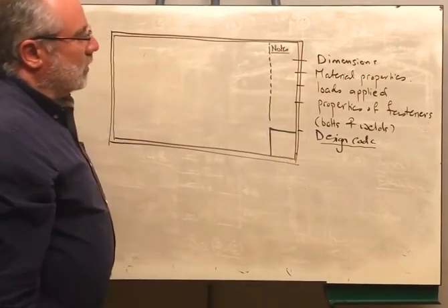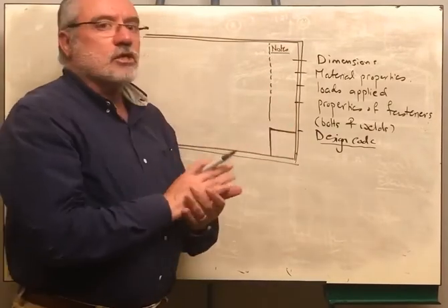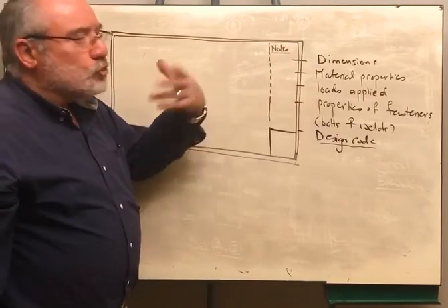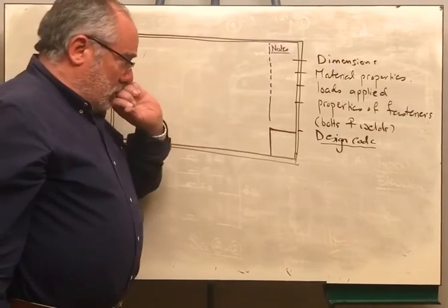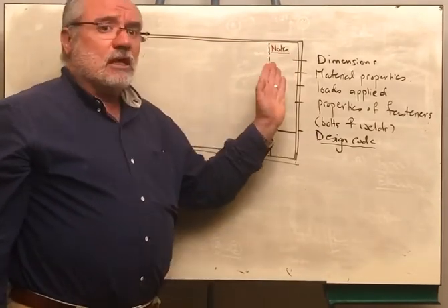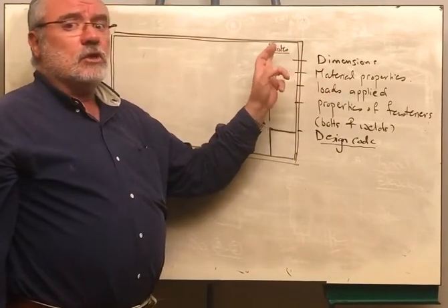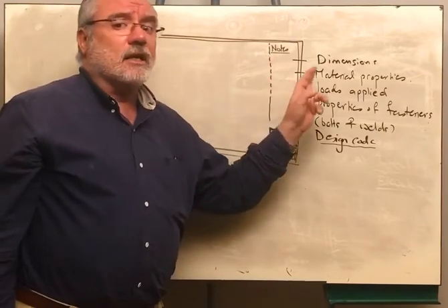If you open my notes, you will find a sample of the general notes that we are applying in the steel structure. Well, this is optional, but you should learn that whenever we have any structural drawing, we have to give indication of the units used, the units of the level, the units of the dimension, what kind of material I'm using.